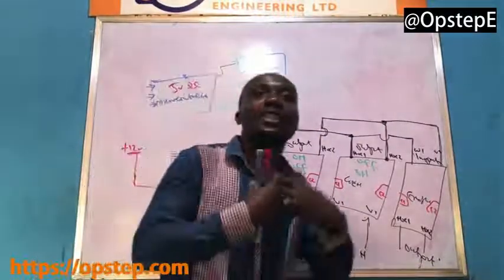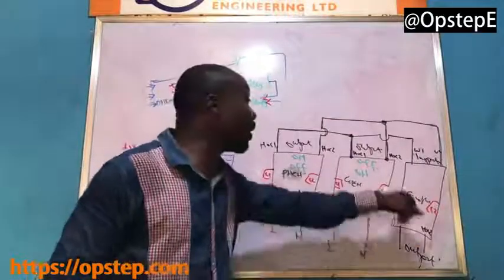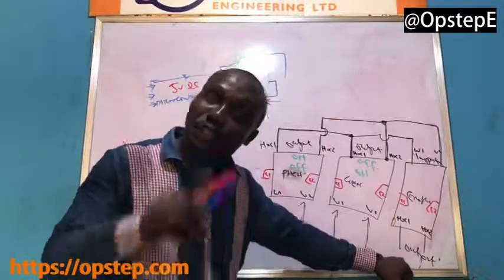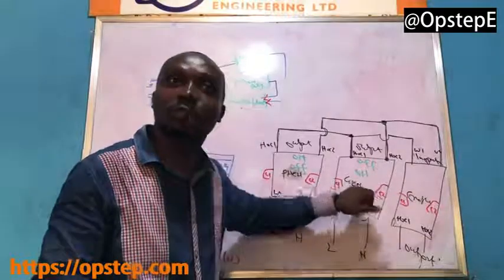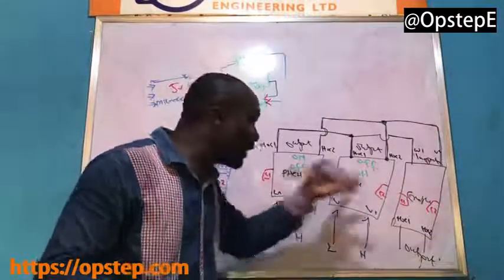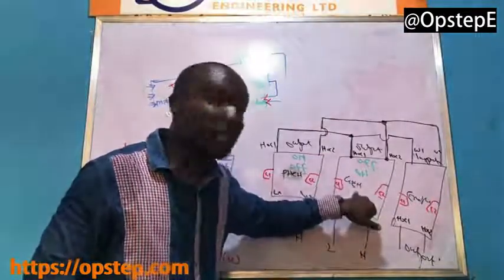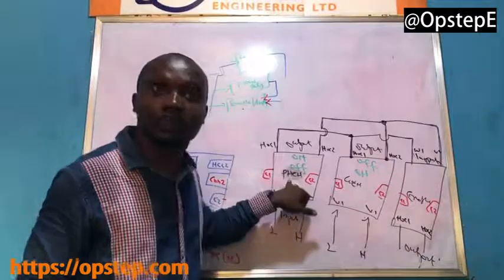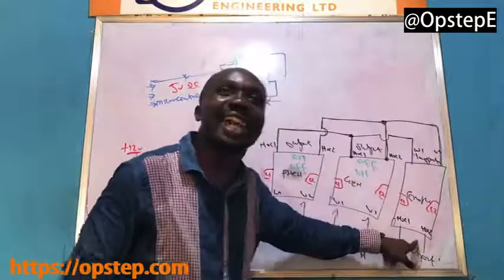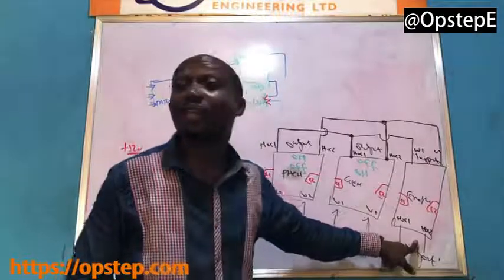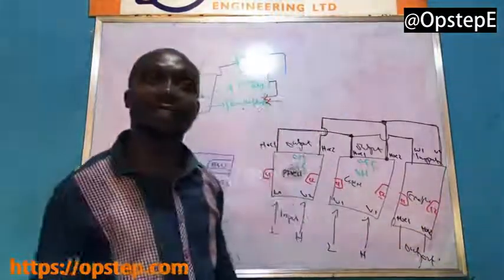So if you say, oh, on generator, it puts on generator. Generator is there. Generator supply is there. Doesn't mean that you have it at home. No. Your next responsibility is to say, oh yeah, on generator coil, which is you are switching source. I want generator as a source. So you enable the coil of this relay, and put up the coil of this particular one. So the voltage is here, but the voltage is not yet here. The next instruction you tell it is what? Enable this guy, then that's when you receive the voltage.